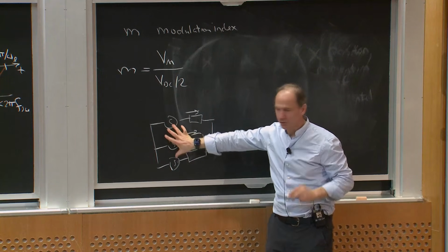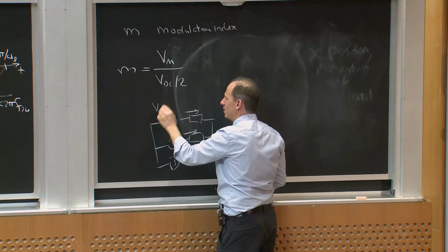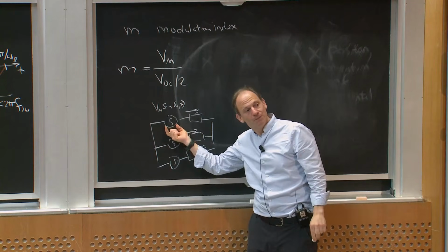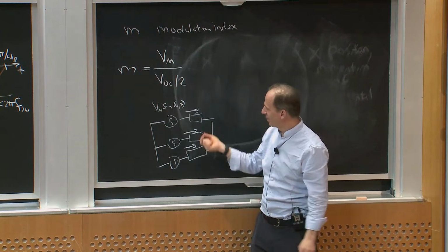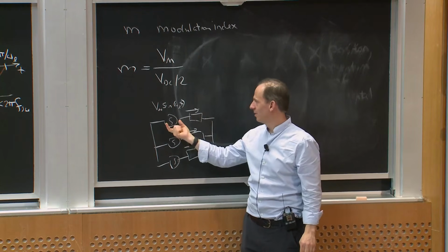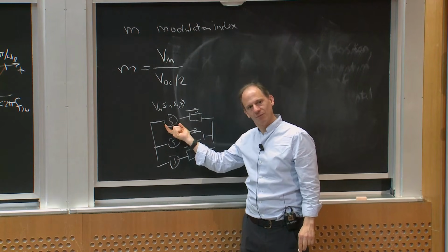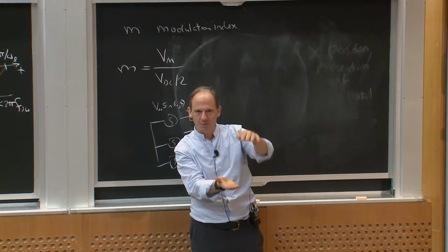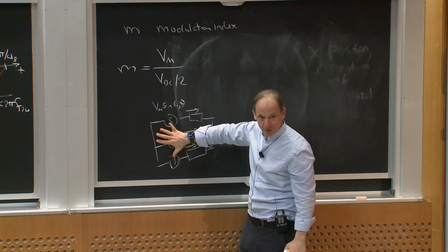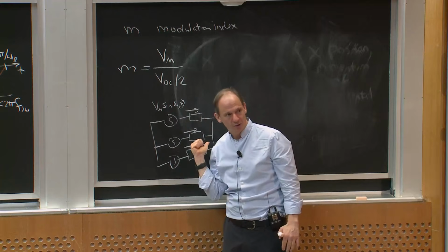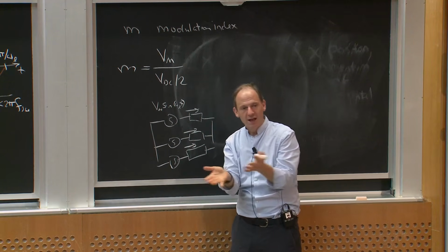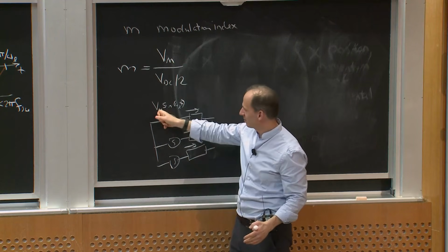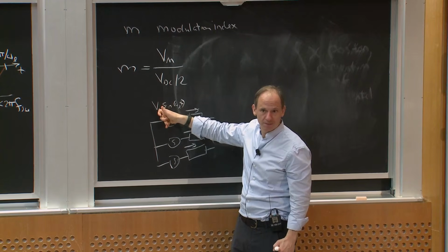These are now at the line frequency. These are V sub m sine of omega line t. I want these voltages to be small. But as speed goes up and the back EMF internal to the machine goes up, I want a bigger V sub m, for example. So very often, by changing the V sub m, by changing the amplitude of my reference, I change these voltage amplitudes, and then I change how much current I'm driving into my load. So I often want to modulate that. And typically, as I'm going up in speed or going up in power or both, I'm trying to make V sub m bigger. Does that make sense to everybody?